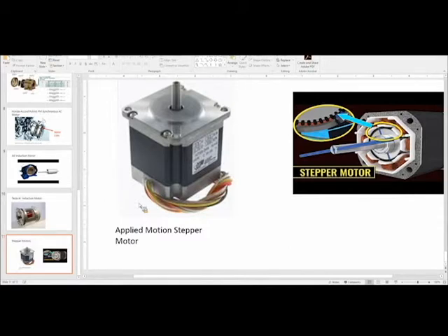Then this one's turned off, and then B is turned on. Therefore, to minimize this reluctance, the system rotates this tooth of the rotor into place, and then this one rotates in place as well. So it's actually a lot more like a solenoid than other motors. If you de-energize coil A and energize B, it becomes clear that the rotor will rotate as shown. From the geometry, it is clear that the one-step size is 30 degrees.